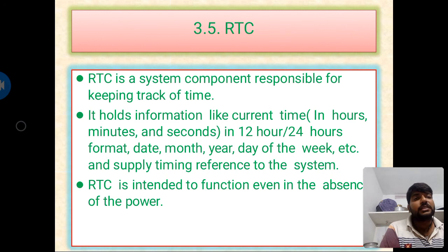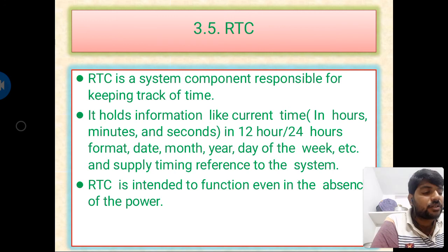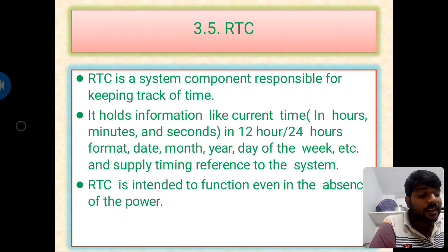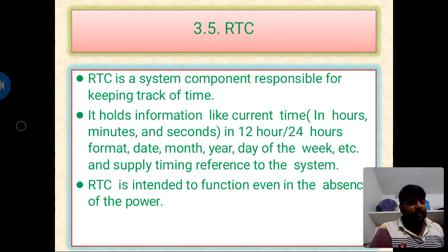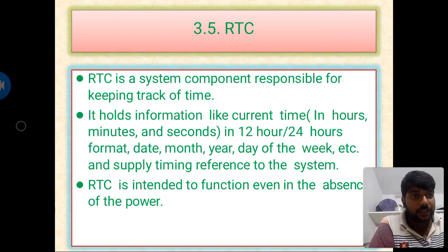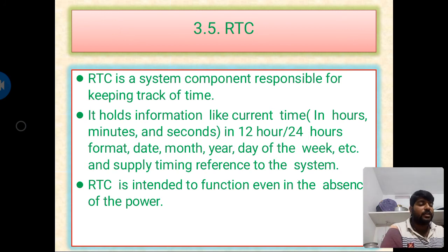So one more circuit is also required as an external component, that is the brownout protection circuit. In the embedded system, the brownout protection circuit is used to protect the processor or controller program execution when the operating voltage drops below the threshold level. So when the operating voltage is below the threshold level, automatically the brownout protection circuit is used to protect the processor or controller. So it is used during power-down conditions. The voltage level is below the threshold.